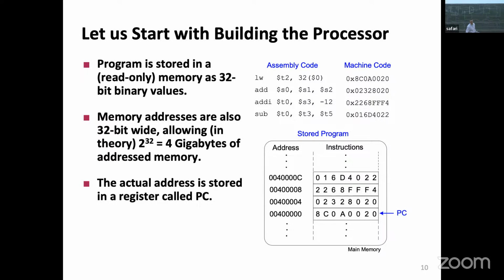And this, we were never writing to the memory before. So in R-type instructions, we didn't write. We definitely didn't write. Here we didn't write. But here, now we are going to write. The ALU operation is the same operation as before. We are still adding the immediate to the constant. And mem to reg, what do you say about that?